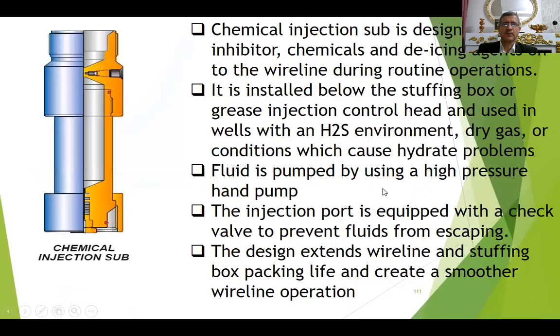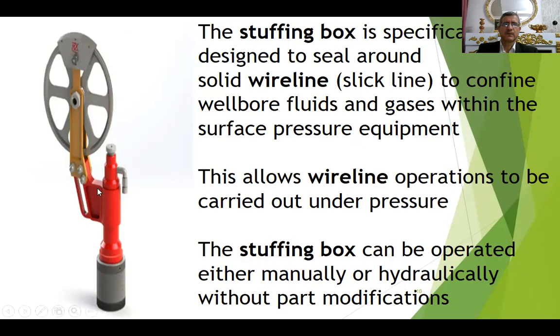So here we have the packing nut. Either we apply hydraulic pressure on it here to seal around the wire using the packing of the stuffing box, or manually somebody will climb up and tighten the packing nut and achieve the seal.